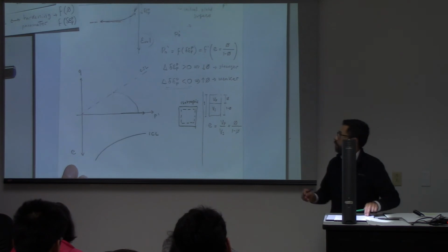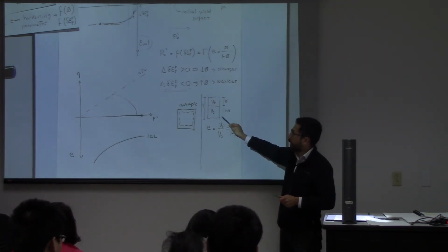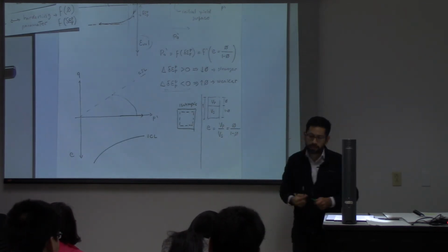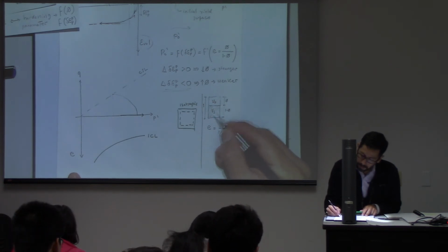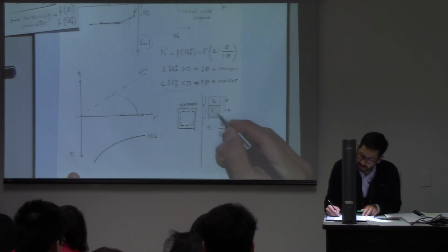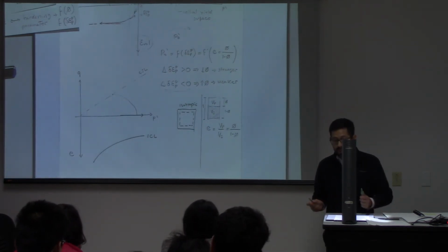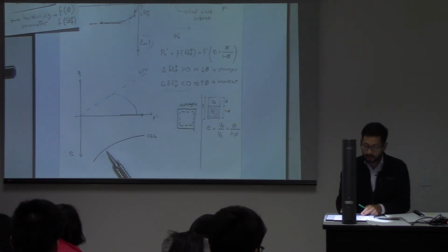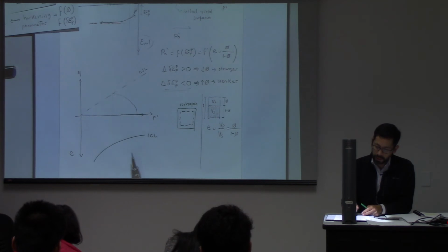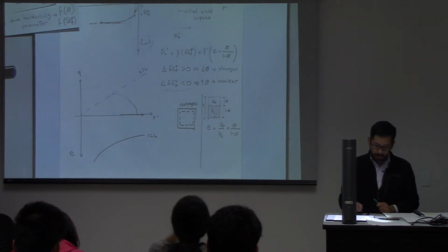I always forget this equation of void ratio. But you just have to draw this. If you draw that, it comes out naturally from that drawing. But it's a parameter which is linear with the porosity. So it is basically a porosity, but written in some other terms. So the higher the mean stress, the lower the porosity or the void ratio. That would be for an isotropic test.